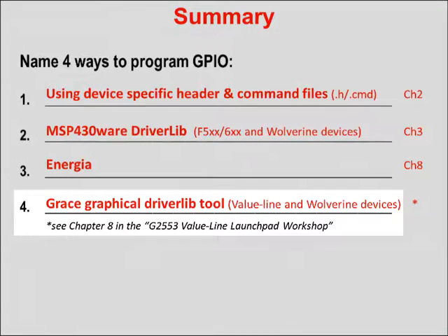The final one is Grace. That's a graphical driver library tool, at least that's the way I describe it. It only works with the Value Line and Wolverine devices as of today, but it gives you a graphical user interface and actually makes programming some of these devices extremely easy. For example, if you're programming one of the FR5969 devices with Grace, it actually outputs driver library code.